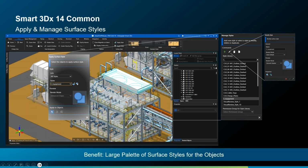Apply and manage surface styles. The list drop-down has all styles in the model or styles used in the workspace. You can select your styles from here, or you can select a style from the graphics using the eyedropper, and you can also manage your styles using this icon here. You will also be able to see the preview of the selected style.